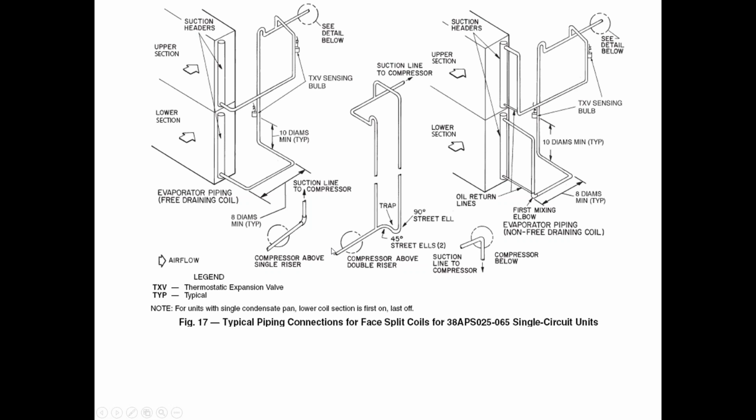And how these work, we'll say we're running at 100% capacity right now. Let's say we've got a 100-ton unit and we're running at 100 tons capacity. Well, we've got enough suction velocity to entrain both oil and suction gas up both the A pipe and the B pipe. But now let's say we start unloading the machine. We've got a 100-ton machine, and this guy can unload all the way down to 7%. So it's going to get down around 9 to 11 tons.